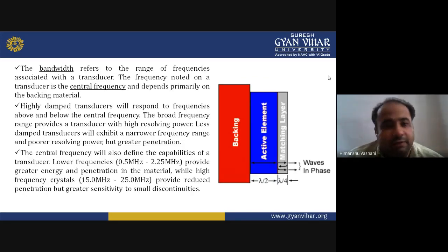The bandwidth that we are discussing here refers to the range of frequencies associated with the transducer. The frequency noted on a transducer is the central frequency and depends primarily on the backing material. Now you can see the importance of the backing material.